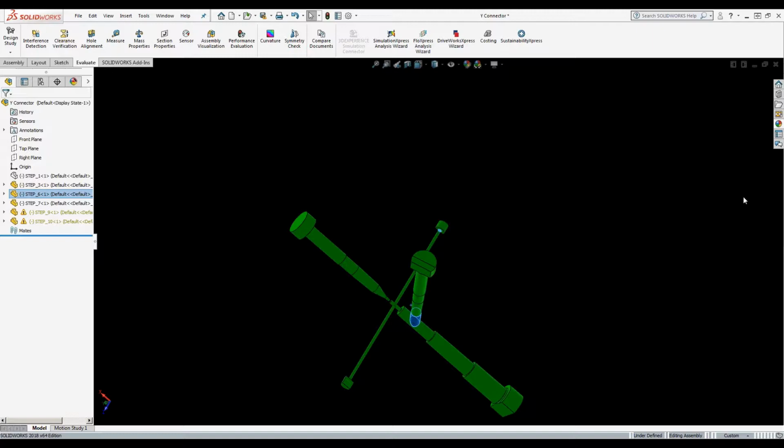So do the transverse pins withdraw prior to injection? With this tool, this was actually a prototype tool, so everything was manual, hand loads. So the part would be ejected with all these pins in it. The only pins that would be in place are the 2 smaller ones. Those are housed in the core and cavity.